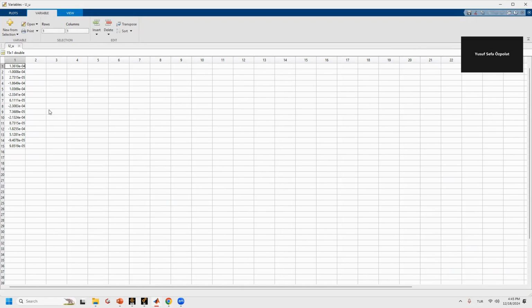As you can see, even though we should have 18 displacement values, for each node in x and y direction, at total 18 values, we excluded the displacement in restricted motions, which is for the fixed support, and the y direction of the roller support.